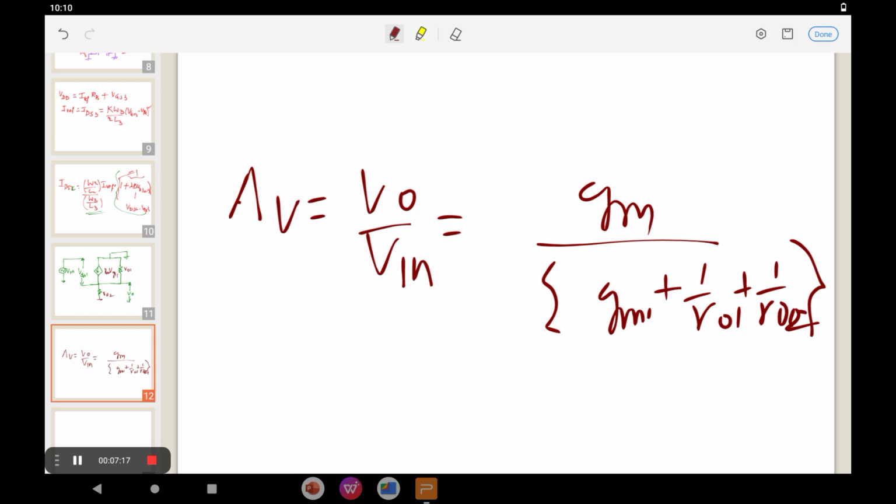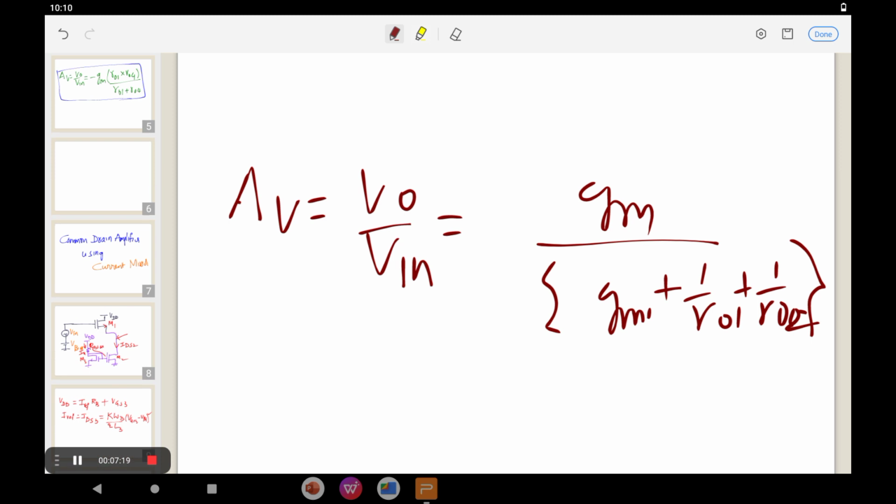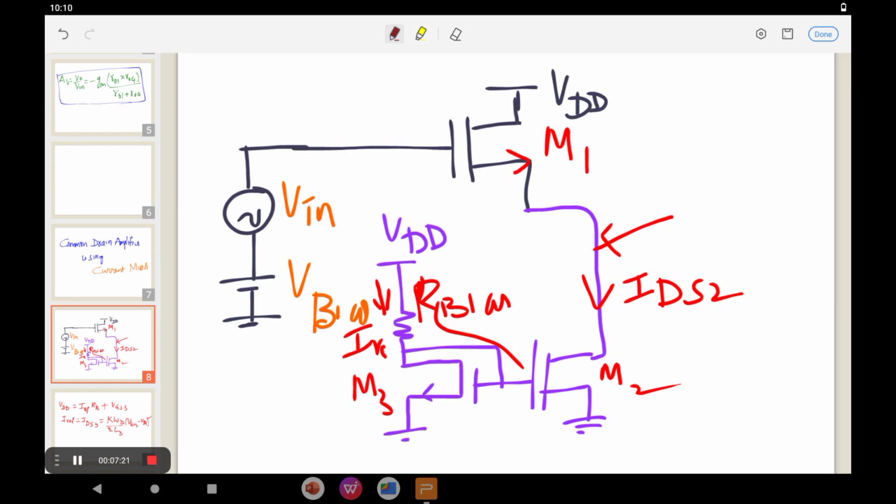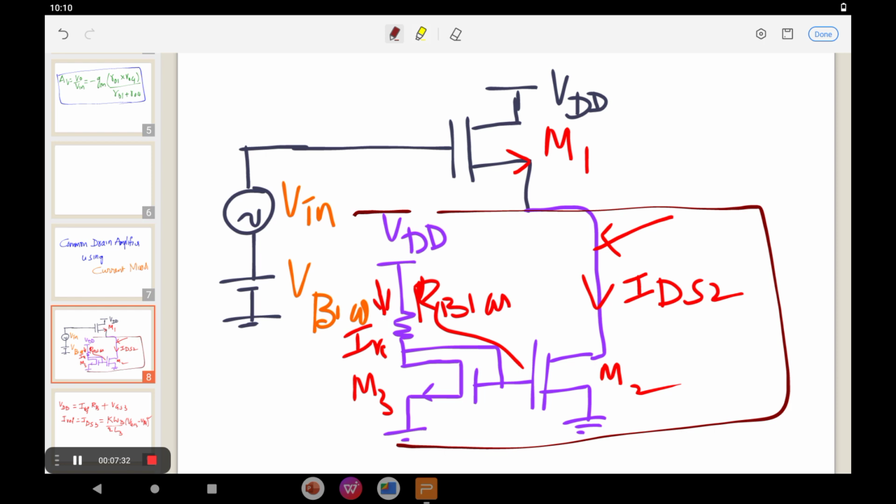The very important consideration here is that in the common drain case, the drain current source is simply replaced with the current mirror circuit. That is the only basic variation. The basic purpose of the current mirror circuit is to produce a constant current source.